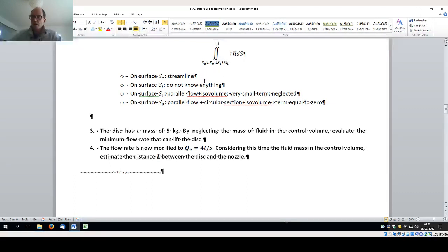Here on a streamline, it's also a very small term. You see at the interface you have water flowing here, and you have air. So the air is getting at the same velocity than water here. So you may have a small viscous contribution at the interface, but it's usually very small, and at least in this condition, where you have effect of inlet, the free surface, the outlet, those terms will be very, very small compared to here.